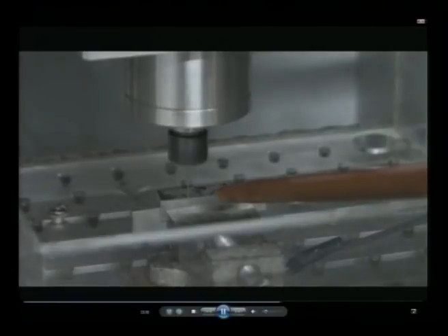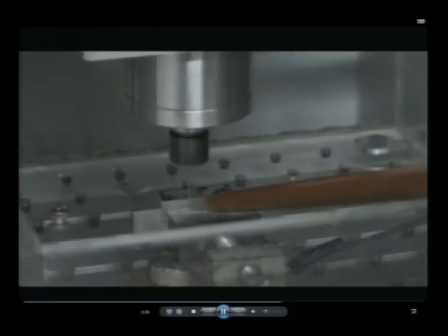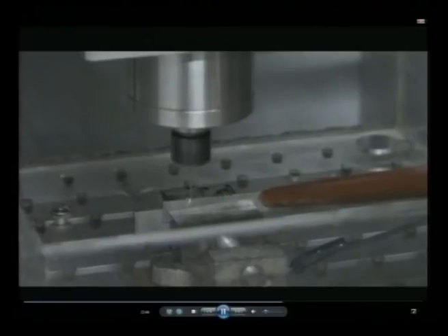Now the tool of defined diameter is moved towards the workpiece. Now the spark has started. Now the material is removed from the workpiece. This is the advantage of this process. Simultaneously, a tool can be prepared from the block and can be used to machine the workpiece.